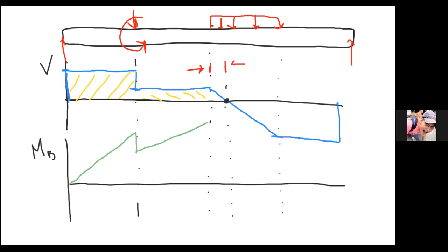And the way that I do that is this is in between C and D, which is the equation that I found. So I would go ask myself, hey, if I set v equal to 0 in that equation, what is x equal to? X should be equal to 11.1875. So we know that this distance is just that 11 value minus 9, which is the amount to the left of it. That makes it easy to figure out what the area of that little triangle is.